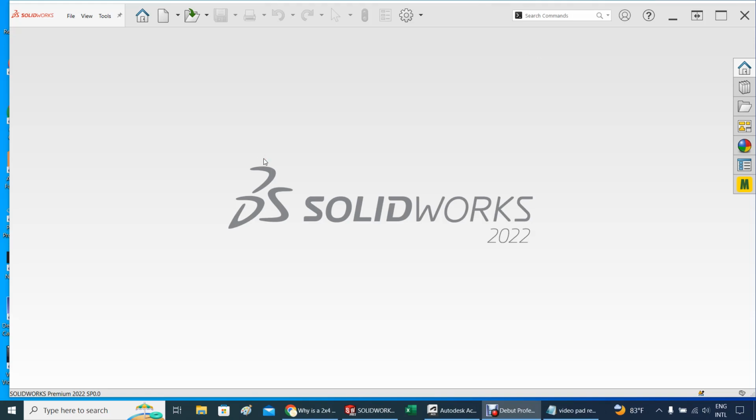We're going to be working with wood, and one thing that you quickly discover is that SolidWorks has very little profiles about wood. So I'm going to be using a 2x4 in a project, and actually, that is not a 2x4. I have to put the real measurement, which is 1.5 times 2.5 or so. So we need that profile. If you don't know where they are, you always need to look for them.